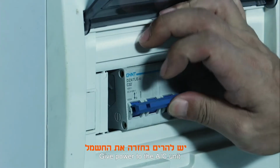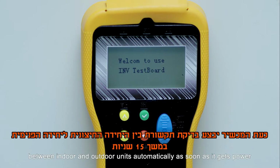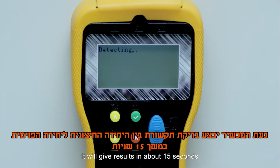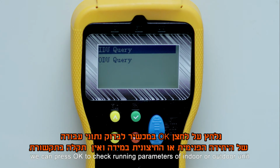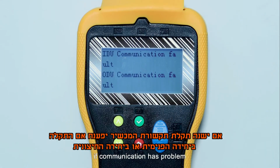Give power to the air conditioner unit. Dr. Smart will check the communication between indoor and outdoor units automatically as soon as it gets power. It will give results in about 15 seconds. We can press OK to check running parameters of indoor or outdoor unit if communication is normal. It will tell you indoor or outdoor unit communication failure if communication has a problem.